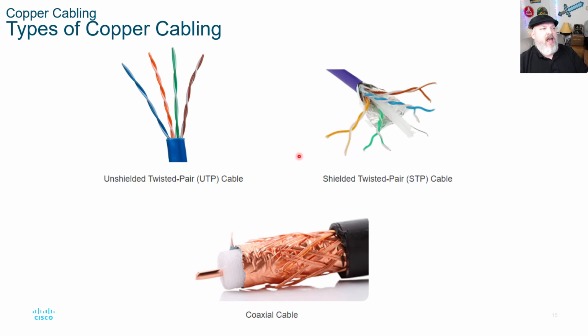This cabling is more expensive because it costs more money to put that metal shielding around it and the twist. Another note, outside of the classroom, from my personal experience: some cabling will be more expensive and some less expensive. You want to make sure that you're checking the twist per length, twist per yard or twist per foot. Some companies calculate it differently.